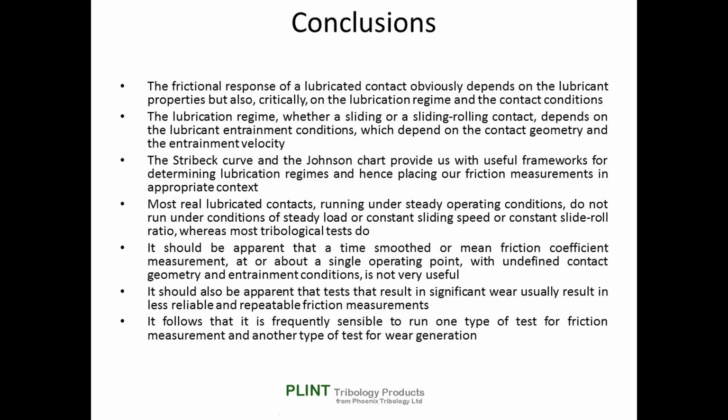It should be apparent that a time smooth or mean friction coefficient measurement at or about a single operating point with undefined contact geometry and entrainment conditions is not very useful. It should also be apparent that tests that result in significant wear usually result in less reliable and repeatable friction measurements.